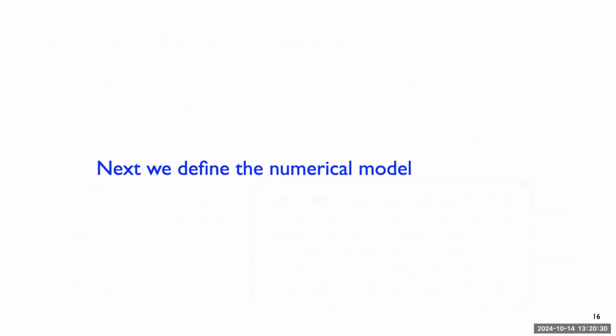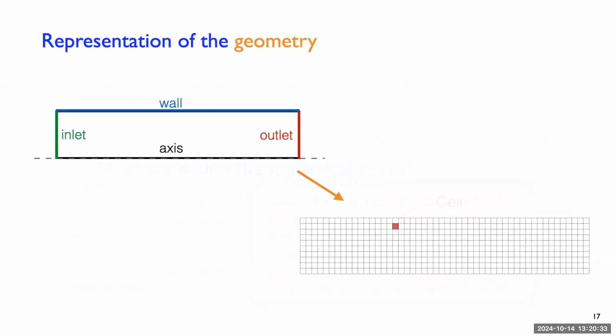So that's the model, and you can see that may have already introduced errors. Then the numerical process also introduces errors. If you remember, we took our idealized geometry and made a discrete version of it. We represented it by squares, triangles, a so-called mesh or grid. If we had a curve, we've no curve here, but if we did, and we're using straight-edged shapes, then that will be an approximation of the geometry. So you'll have a geometrical error as well. The discretization error has a geometric component as well as, let's say, the classic mesh interpolation error.